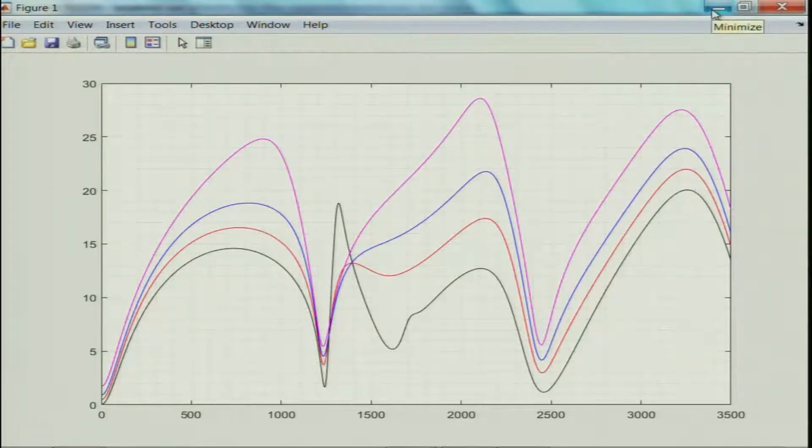So notice one thing, that we have completely ignored the convective effects of mean flow. That will be quite tedious to incorporate if you need to have the B inverse A matrix and do all those things and get approximate expressions for M2 within the cavity, and it's going to be very tedious. So that would have just changed the dB value by a few dB here and there. So we will be contented with ignoring the convective effects, and just focusing on these values.